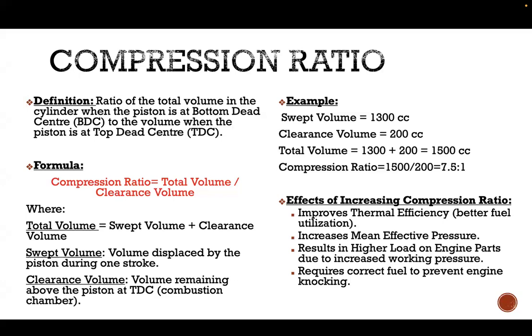So we have to choose a fuel for that particular engine where you're going to have the right amount of compression ratio. At the same time, for whatever compression ratio we get the best thermal efficiency, and it all happens in a sequence. Whenever we have combustion, it should be when we give a spark. Other than that, we should not have combustion because it is going to decrease the efficiency of your engine.